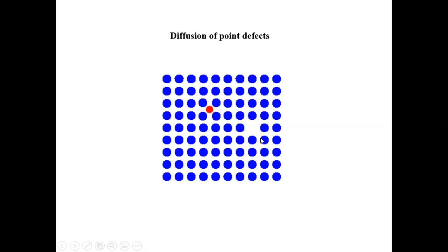Okay, so what do you call this type of guy, which is gone here? Vacancy. This is a vacancy, right? And although this vacancy is not a real particle, if you imagine that I have an imaginary particle, you can see the vacancy is also diffusing around. At some point, it sees the interstitial, and the interstitial jumps into the vacancy. But anyway, the whole point to show here is that you still have diffusion, right?